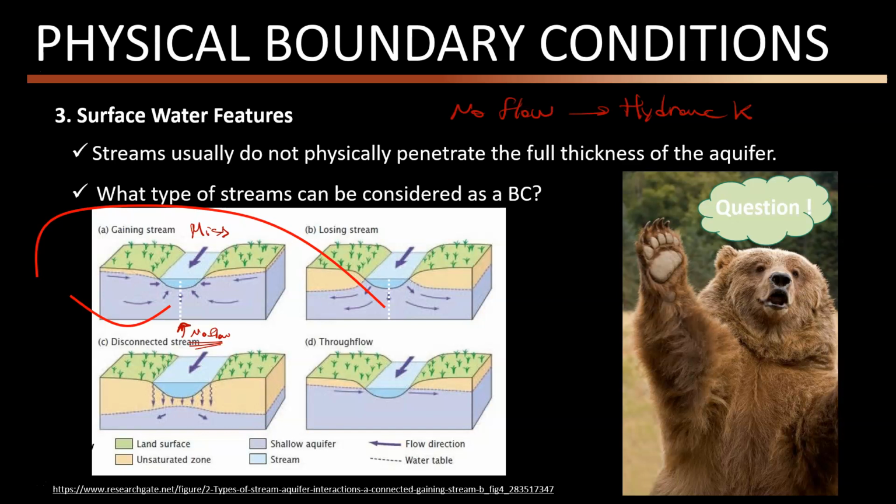If you look at the flow direction here, technically we assume that there is a vertical flow. The groundwater gets into the bottom of the aquifer vertically here, and again here, but in the other direction, the groundwater gets into the system vertically here. So it means that the water cannot move horizontally, or if there is a streamline here, the streamline comes here and goes up like this. So this streamline cannot pass through this line.